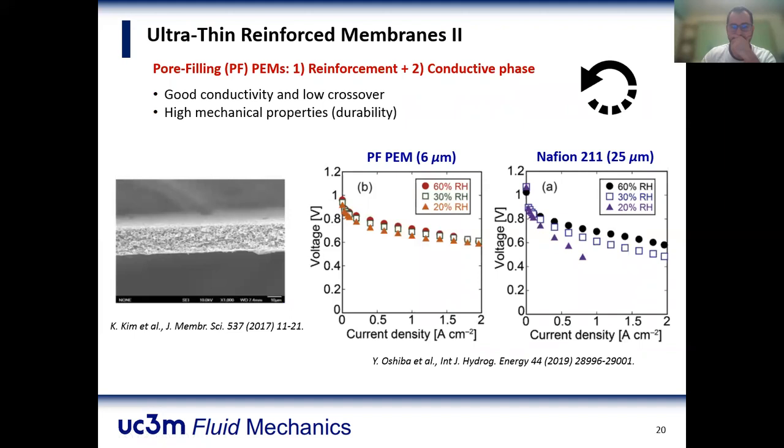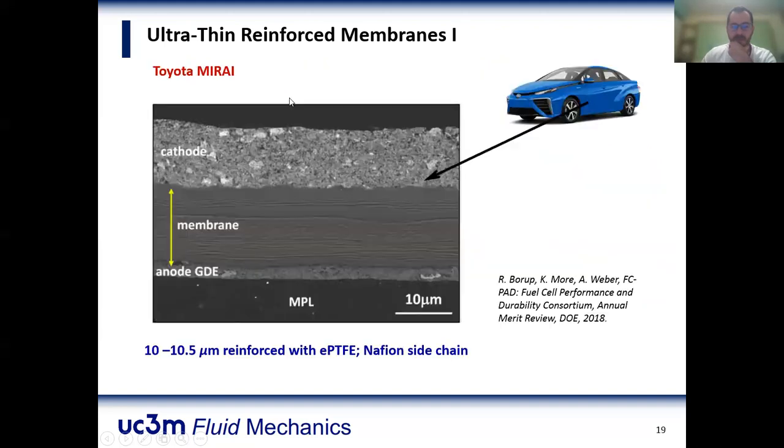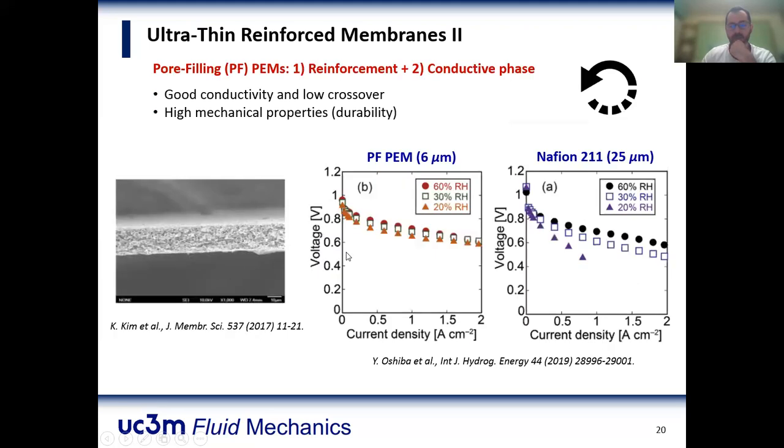We also have some prospects for producing reinforced membranes. We have this approach now with the Teflon introduced into the membrane to put in some reinforcement. But then we can also use other strategies. There is one interesting strategy, which is the pore filling membranes, where we put in the reinforcement first and then add the conductive phase. We are just doing the opposite.